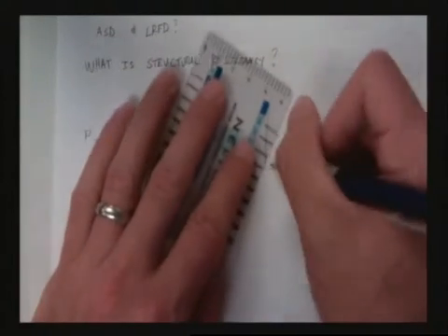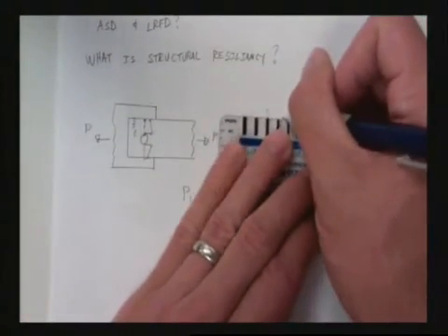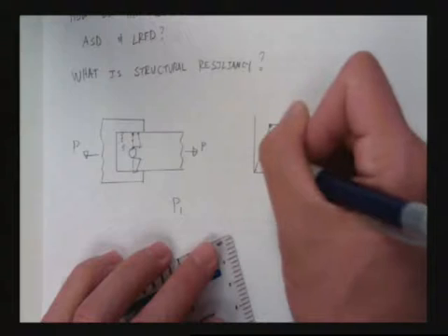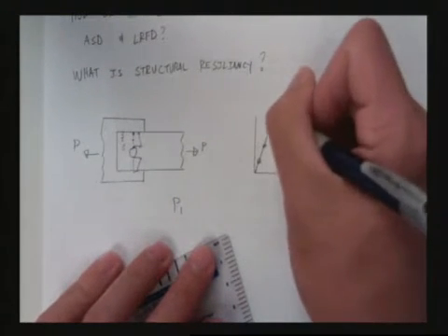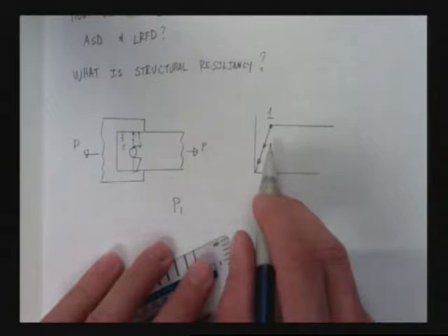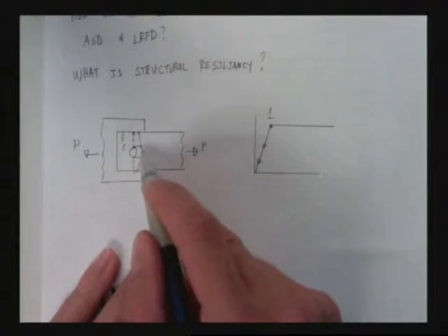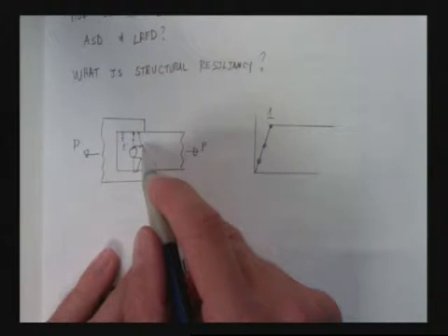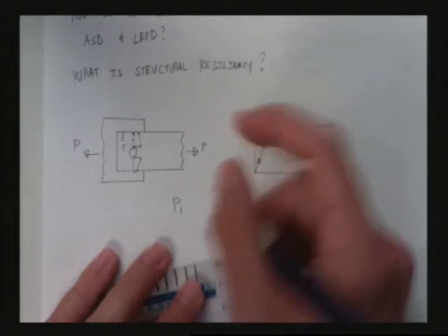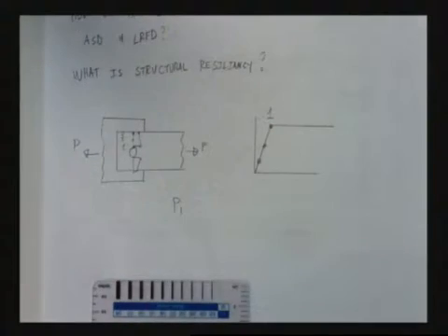Okay, cool. So we'll draw a stress-strain diagram for the material. Say load point 1 may be here, load point 2 may be here, and 3 may be down here. One point's at yield. Yield! Oh no! Who cares? All that means is that little sliver of steel next to the hole isn't as stiff as the material away from it. You with me? So how long can we go on this type of connection? How much more load can we take? What's the limit state?